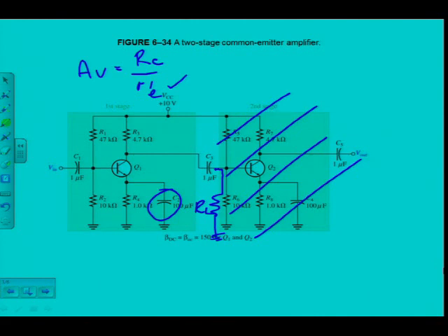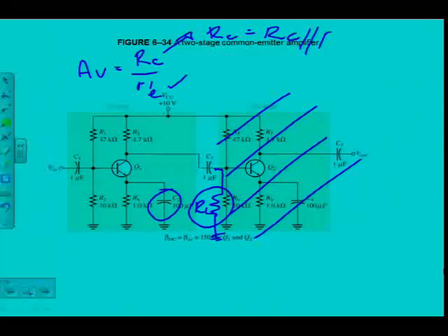Yes. Now let's go on top of the line. What did we say? RC. What do I have to check? RC, when we did the equivalent circuit, would be parallel to what if it is present? Our load, if it is present. If there's no load resistor, then of course this formula would have been true. But now, if I have a load resistor, then I had to calculate R'c, small letter c, which was RC in parallel with RL. You agree? Alright.